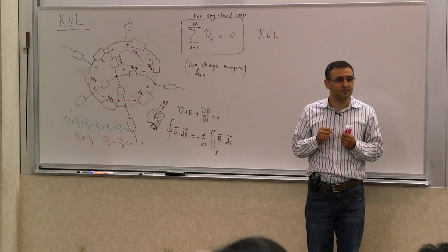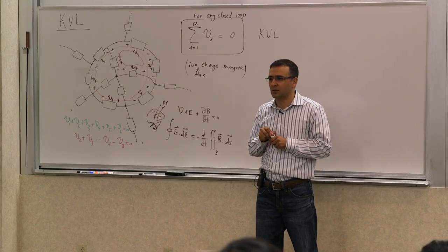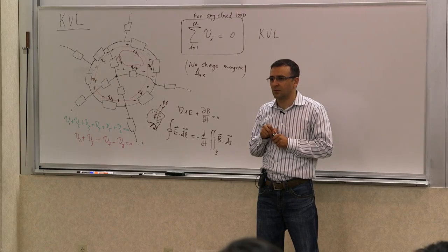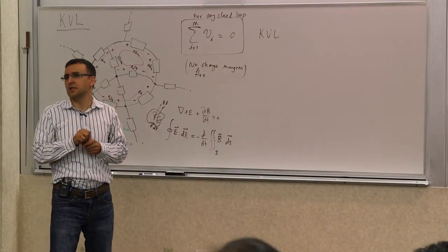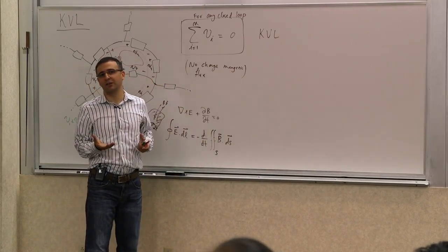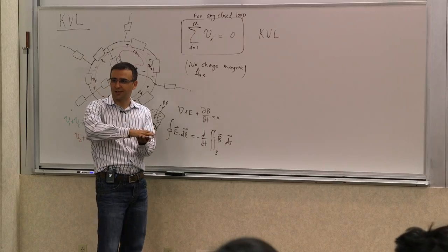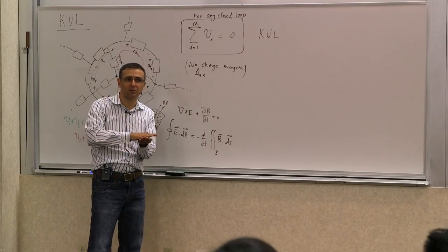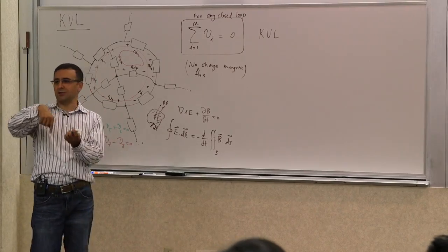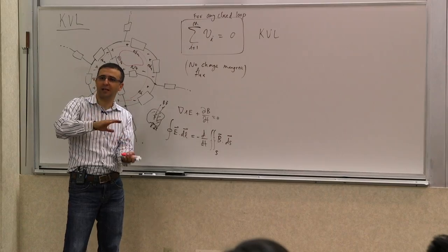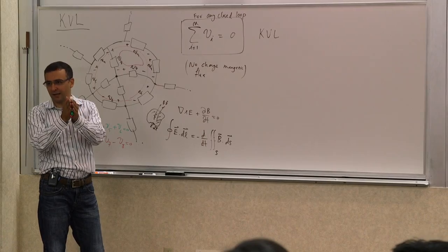All right. Any questions? Yes? Besides antennas, is there any application where you use magnetic flux to violate KVL for some reason? And you mean besides transformers? Yes. If you're talking about KVL. Oh yes, everything. I mean magnetic induction essentially, all of that. You could argue that there's some sort of a transformer, but for these proximity chargers, you've probably seen them with some of the phones. Those are essentially magnetic induction charging. So you essentially create a primary where you alternate the magnetic field and couple energy into the secondary that's picked up. So you do it through space, through the magnetic coupling, without having an electrical contact.